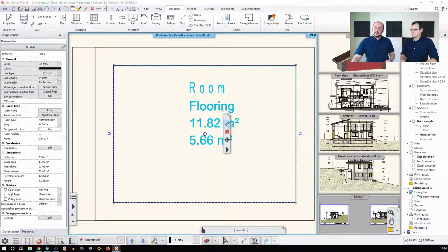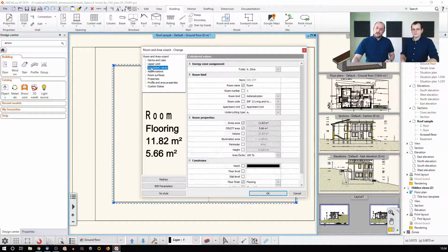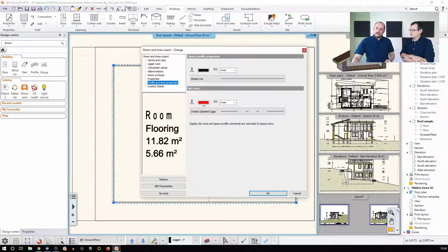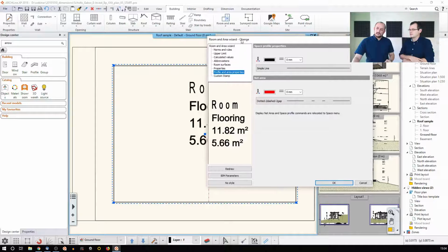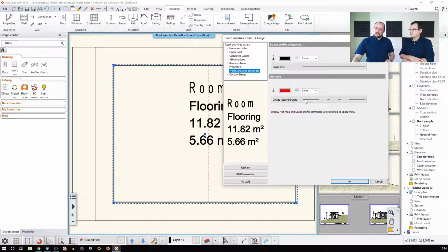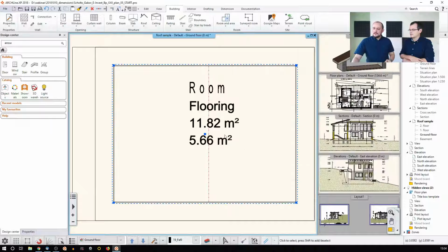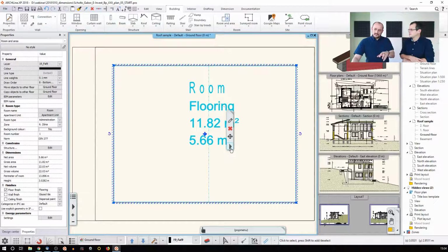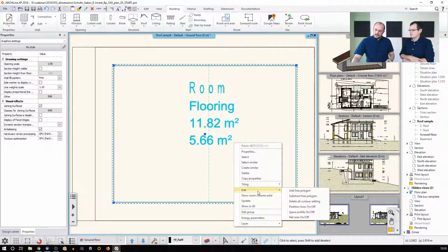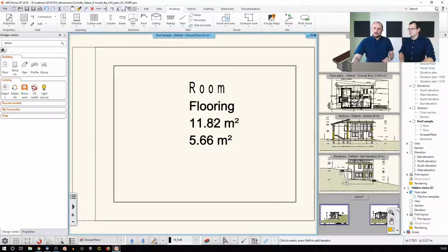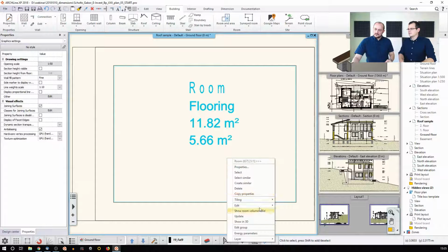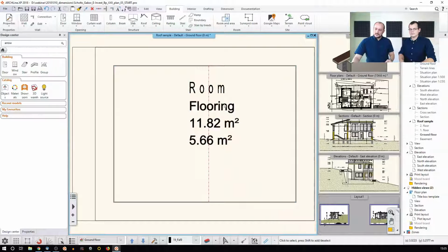So these settings are here. First things first, I activated both of these, and then I went to the profile and area properties, and I just made sure that it is represented red, and with this dashed line. And then it turned this into a visible clue here, until when I already placed it, I used this here. It's called the net area on/off switch. If I just disable it, I won't see it, even though it's there. But if I go back and say, okay, just make it visible for me, and then enable it, then I can see it here.